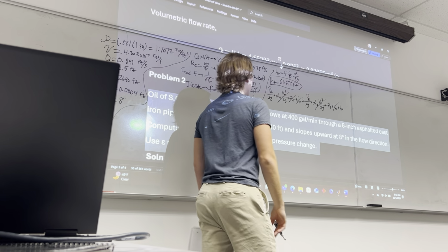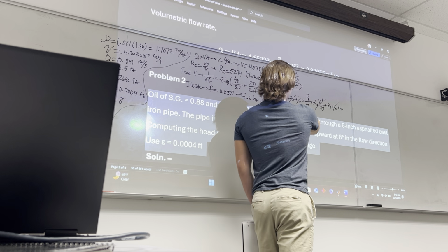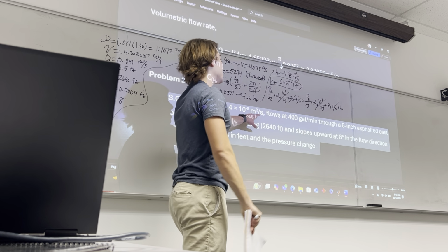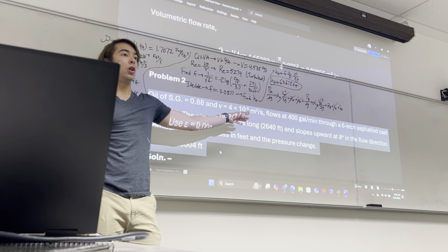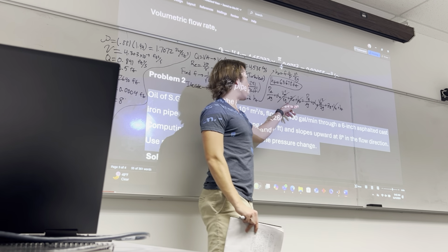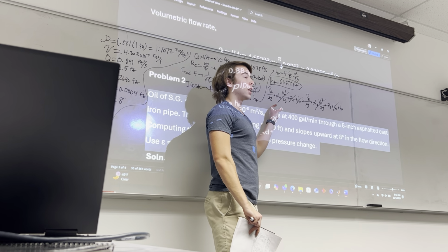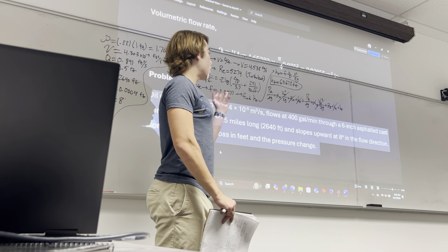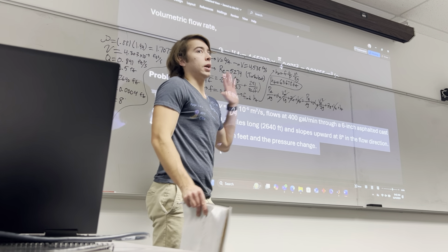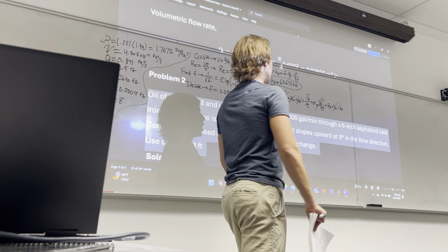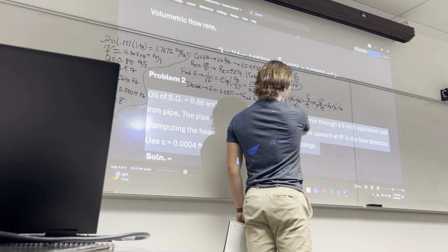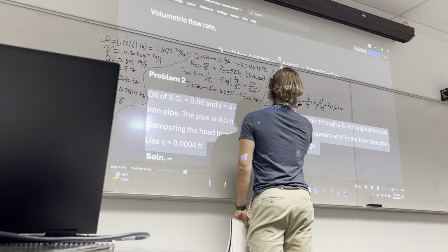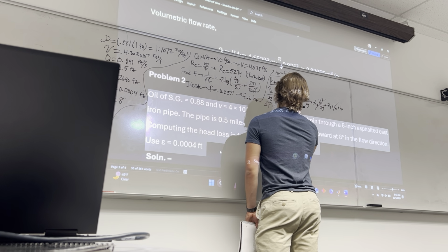So rearranging this, I'm going to multiply the rho G's over, so we can get everything just in terms of pressures. This form of the equation is the head loss form. When you distribute the rho G's to everything and get the pressures as the lone terms, you get it in the pressure loss form. I'm not going to show the algebra for it, we're literally just distributing the rho G's to each thing that's left. So you get PA minus PB, so delta P ends up being rho G times ZB plus HF.